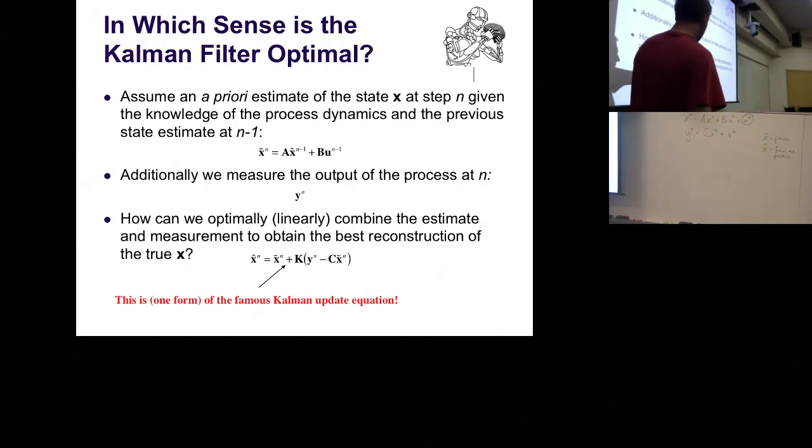In the Kalman filter output, what essentially a Kalman filter is going to do is going to look like that. It takes your prior belief and updates it based on the error between what you're currently measuring and what you predict to measure, and then makes that your posterior belief. I'll show you the derivation. It's going to be too long, but it's not so complicated. This is the famous Kalman update equation, so people know this a lot. The idea is always very simple.